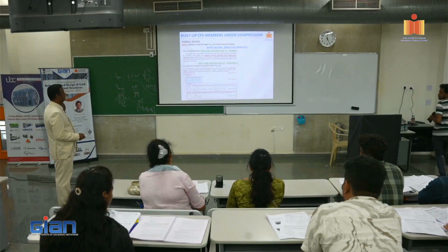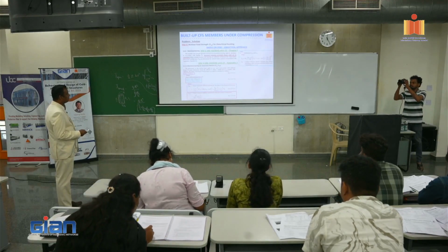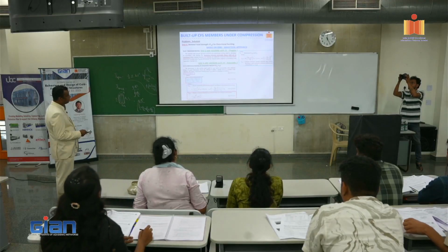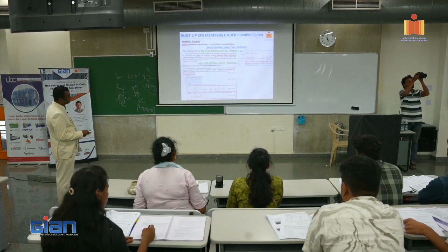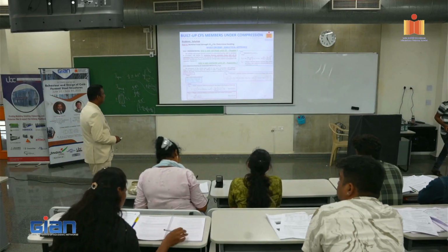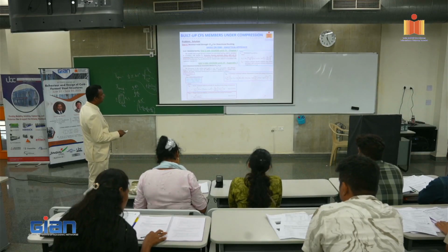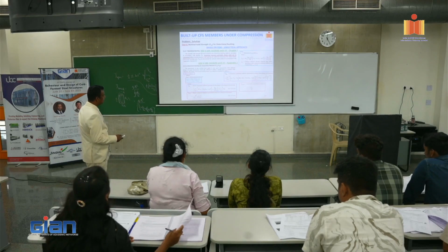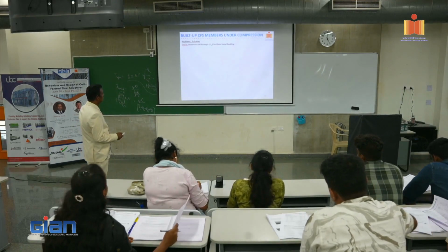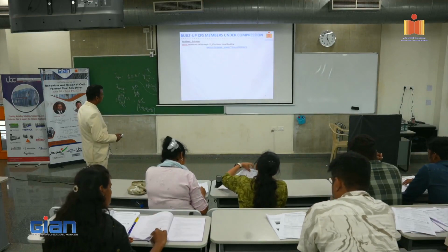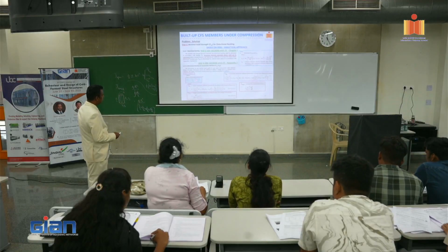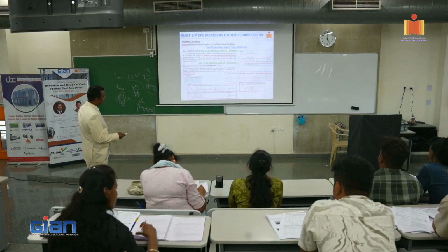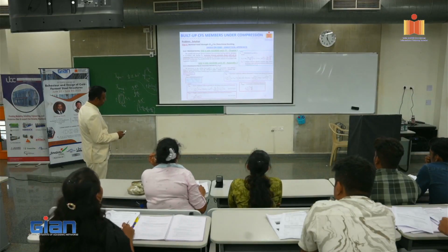So what do we do after this one? I should also calculate this LD because this equation contains LD. What is LD? It is the minimum of LCRD and LM, and we have to calculate LCRD and LM. LM is the distance between the discrete restraints. In our case it is 1800. And then you have to calculate this elastic rotational stiffness, and the geometric rotational stiffness demanded by the flange from the flange-web juncture. And then there is one more thing here. This is the geometric rotational stiffness demanded by the web from the flange-web juncture. Because of lack of space, we have just put it here like this. So we need to calculate all the 4 parameters.